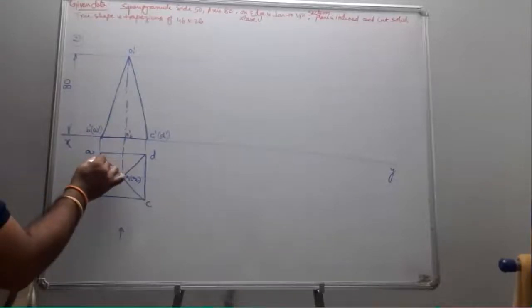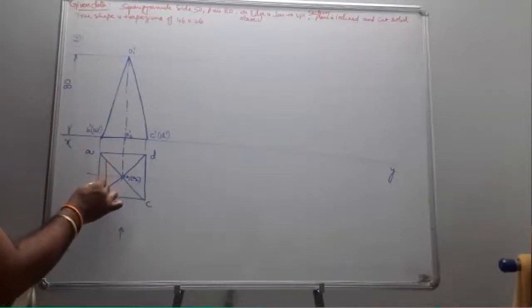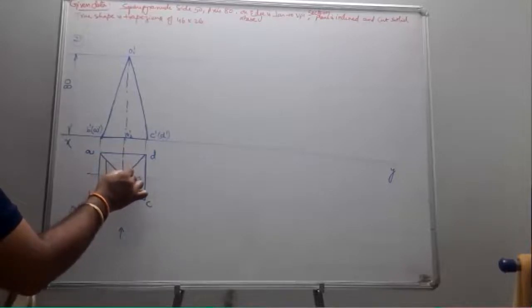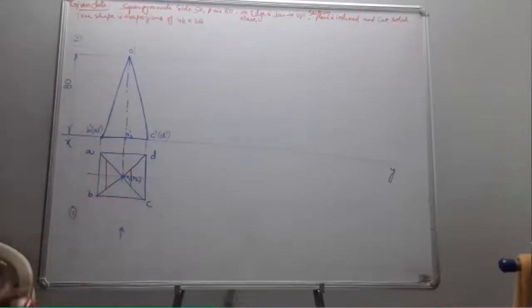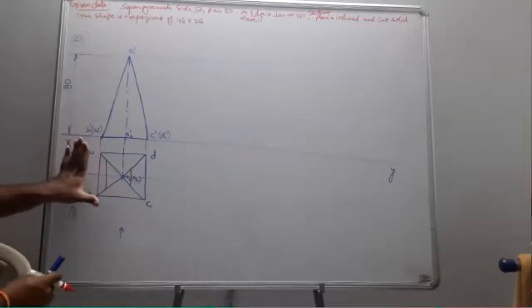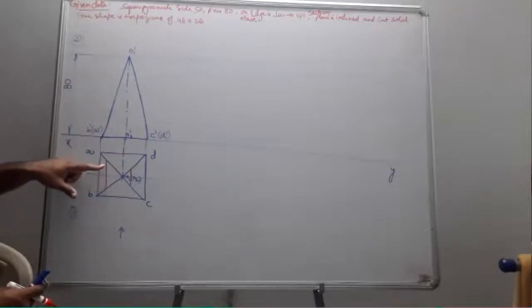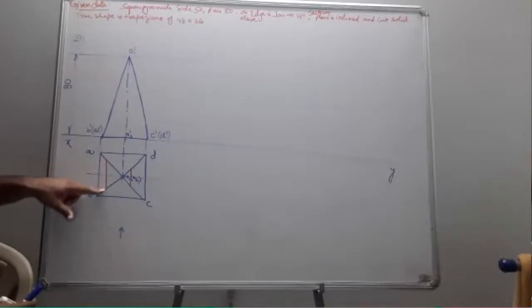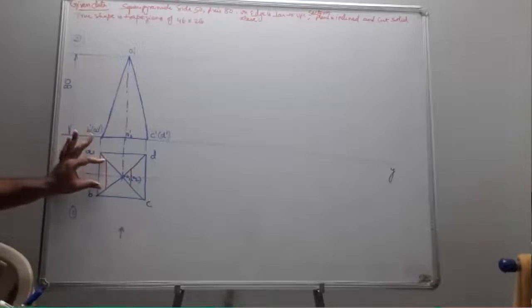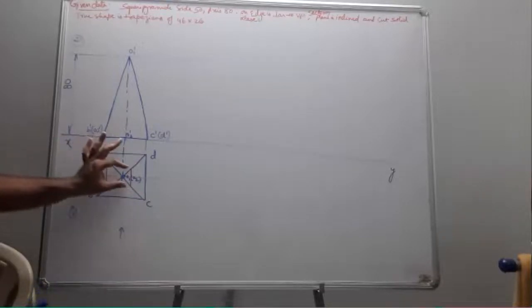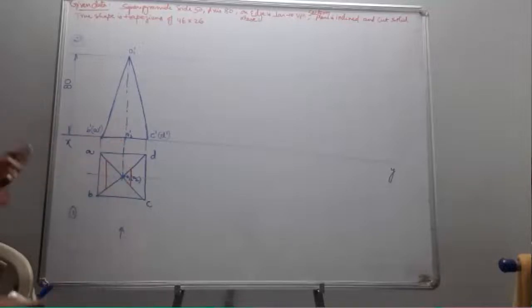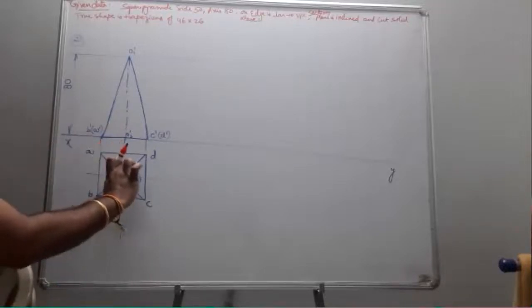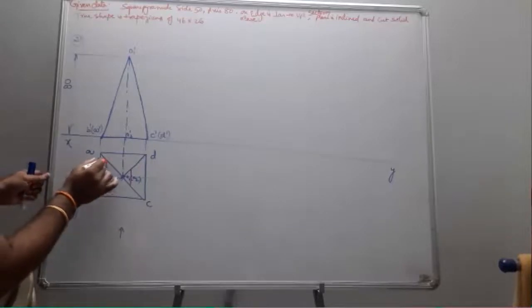This edge is going to be 46 and this edge is going to be 26. He already gives that. So one is 46, one is 26. From this center, I just take your scale, move your drafter scale in such a way that the two edges, OA and OB edges, are going to be cut at a distance of 46 apart, and OD, OC are going to meet at 26 apart. Okay, so this height is 46, this height is 26. Now I am supposed to join these two.